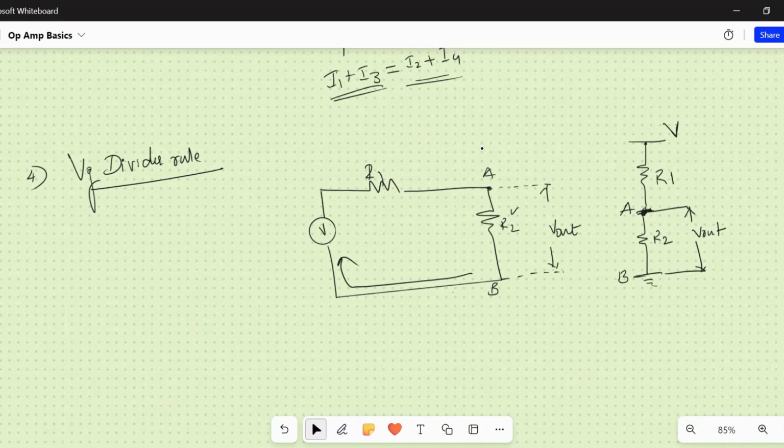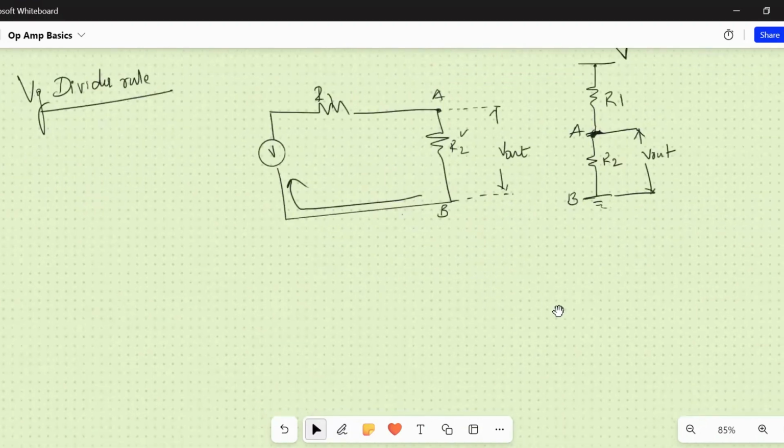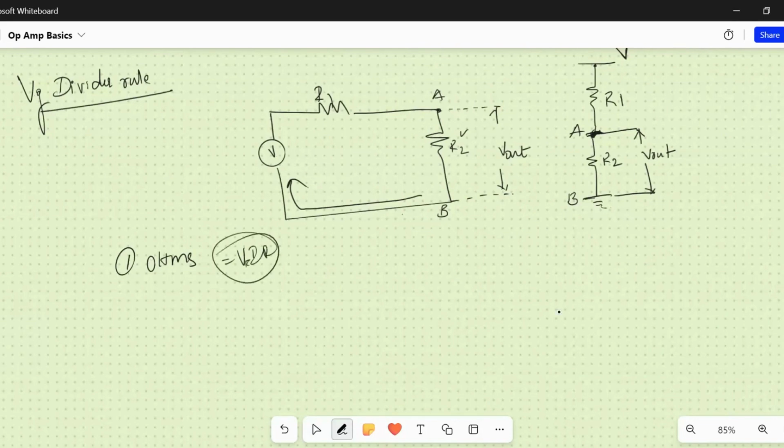I have just written it like this. Now let us try to use, first, Ohm's law. What is the drop across this one? This is a series circuit, so V equals IR applies, right? You should always think of that first. Second, you should apply KVL, the Kirchhoff voltage law. The current through this, I call I. V equals IR is the first one we saw.